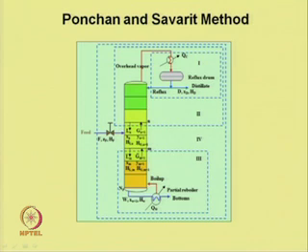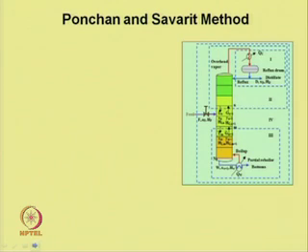Similarly, the liquid stream enthalpy, liquid flow rate and compositions, and the vapor flow rate and vapor compositions are denoted. The bottoms which is coming out is denoted by W, composition is xW and enthalpy is HW. Let us consider material and energy balance equations for envelope 2.